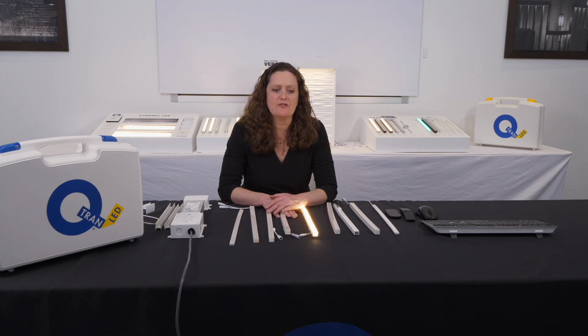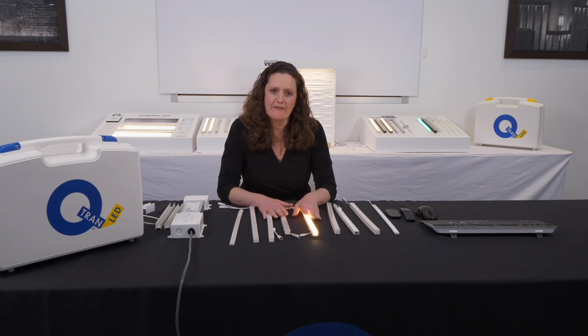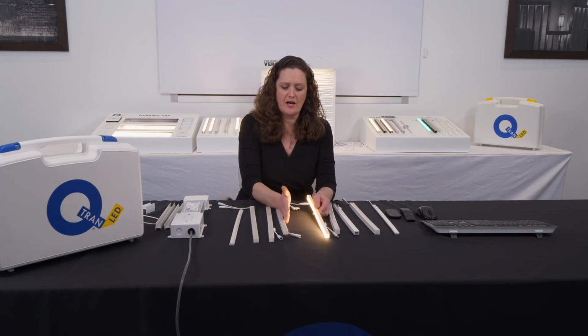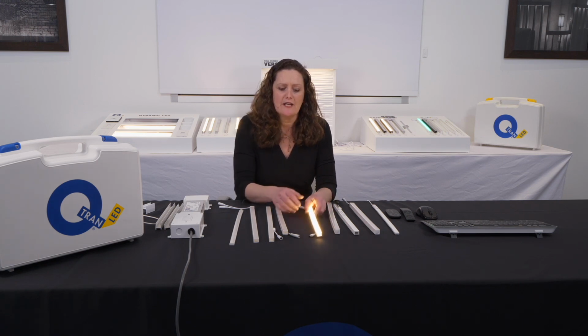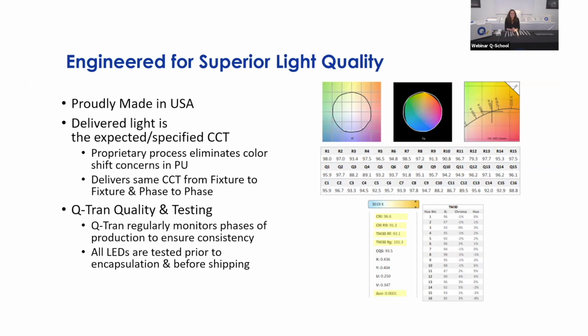And so our engineers have sourced LEDs that perform better when encapsulated rather than what the raw LED is. So that's really important to note, that all those metrics are the delivered DUV, the delivered CCT, the delivered R9. So it's this color coming out of the fixture that we're measuring, not the source LED. And all that's been engineered to give you consistent quality of color and delivered light out of your fixtures. Absolutely, Maura. Thank you for that.